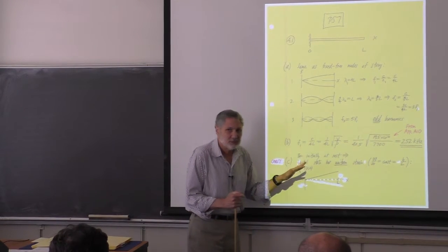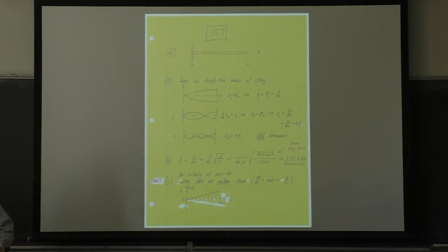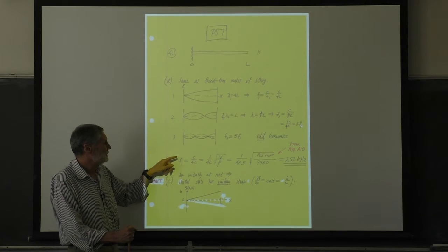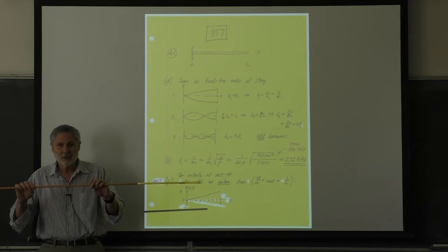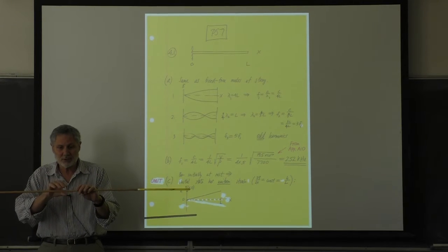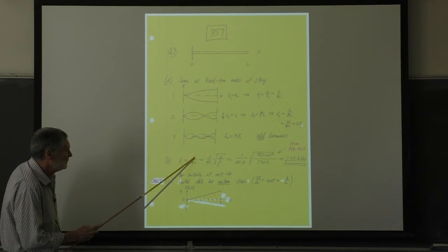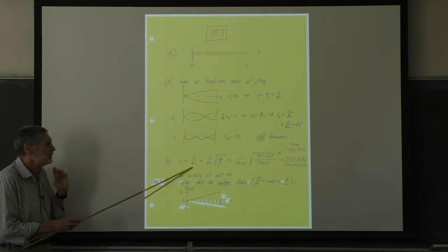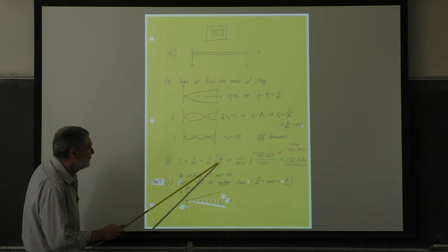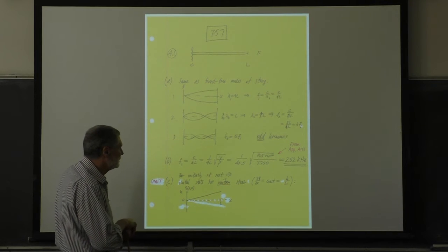So you'll notice here it's got a lot of tabulations of quantities, and you can look up whatever material this is. I don't know what material this is. Steel? Okay. You can look up the speed of sound in steel, speed of longitudinal waves in a steel bar. And it's presumed there that the wavelength is large compared to the diameter, so it's Young's modulus. You actually don't have to substitute in what C is. It's the square root of the Young's modulus divided by the density. You can just look this up. It's easier to do that. But however you want to do it, I did it the long way here. You get about 2.52 kilohertz.